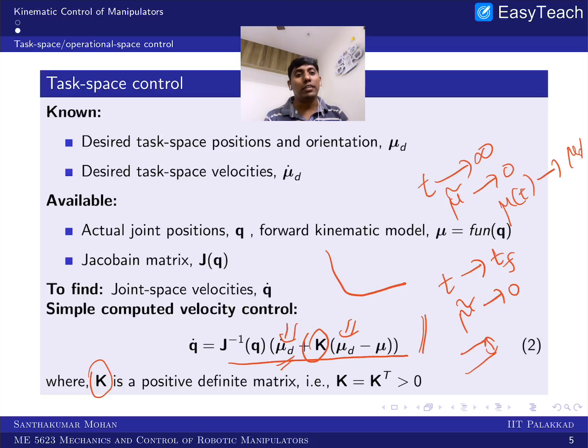So we can see modern control also coming into the picture in robotic manipulator control. And further, in manipulator theory, the kinematic control is not so popular. Why is it so? Because the manipulator is in 3-dimensional space, obviously the manipulator is huge, and inertia and gravity are involved. You cannot make it a simple kinematic control system; realizing the system dynamics simply at a kinematic level is not possible. So in a robotic manipulator, motion control means dynamic control, and force control means dynamics with motion control.